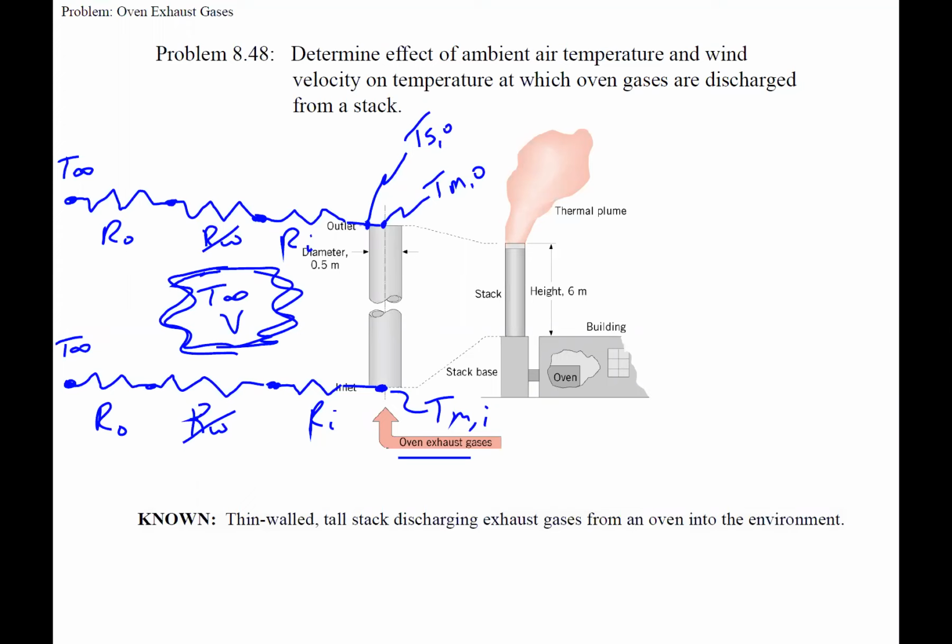As the exhaust is going through the stack, the temperature of that exhaust is changing, right? As we're going from here to here, the temperature is changing of the exhaust. So because it's cooling as it's going through, because T infinity on the outside is cool, right? So it's changing temperature. So that means as we're going through, the wall temperature is going to change, which is that case right there.